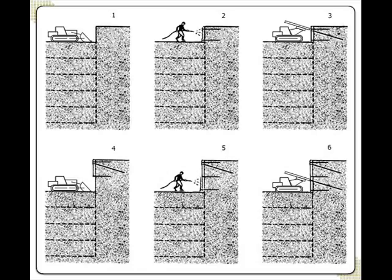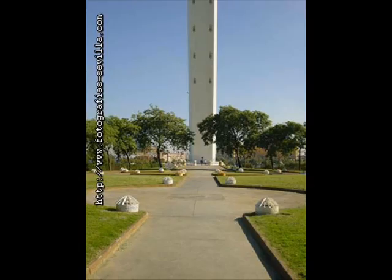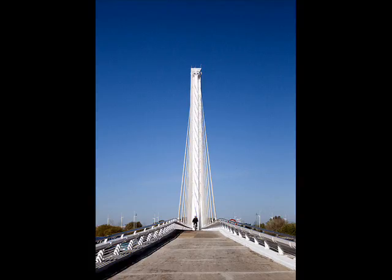The design of this bridge consists of a single mast or pylon of 140 meters of height, which supports the entire weight of the deck of the bridge through a pair of suspenders. It's considered the first bridge supported by cables in which the platform is balanced by the weight of the tilted tower. Between the mast and the deck there is a balance of forces which acts on the 13 pairs of suspenders of 300 meters of length.